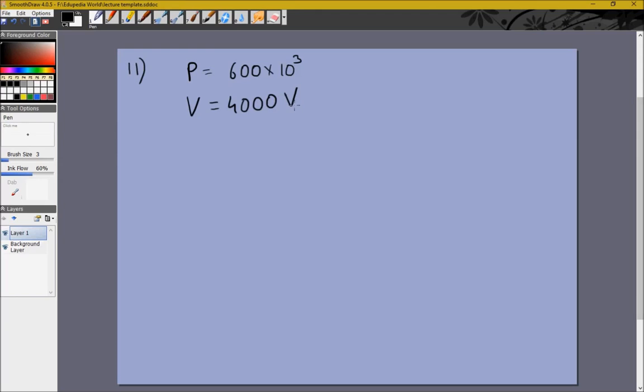So what happens is, because the power and the voltage are fixed, the current will be fixed, and this is the voltage at which it is being produced. This is not the voltage at which it is being necessarily transmitted. So from this you get a particular current. I square R is the power dissipated. So the greater the current is, the more power will be dissipated. So in order to decrease current, we can increase this potential by using a step-up transformer, then transmit it to reduce loss of energy, then decrease potential again, right? So first we're doing the first method, and then using transformers.